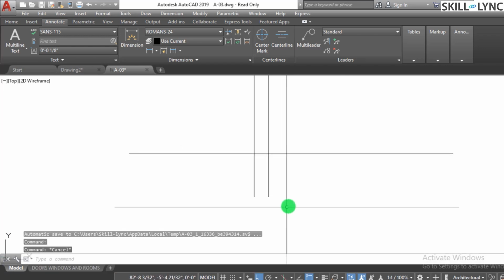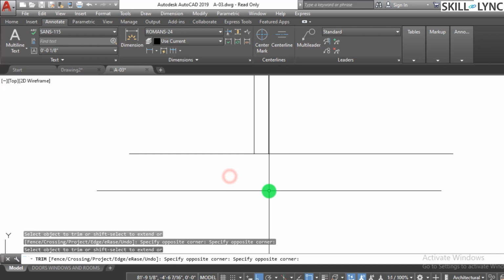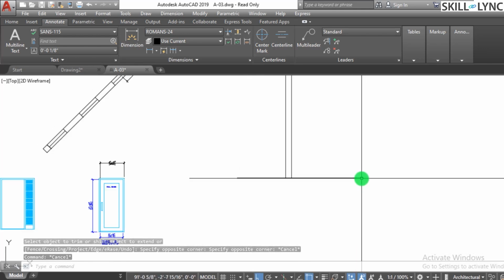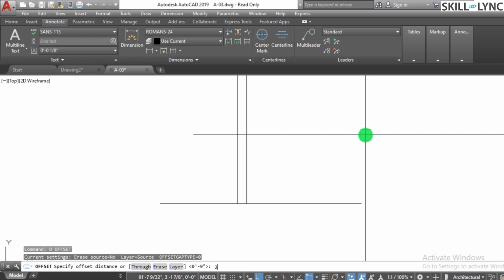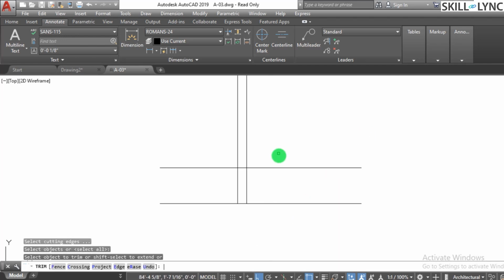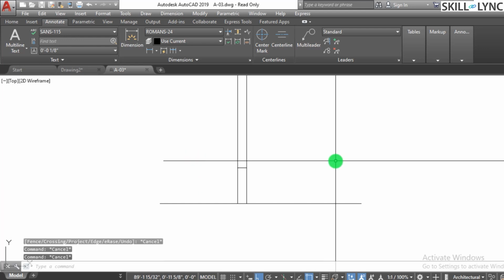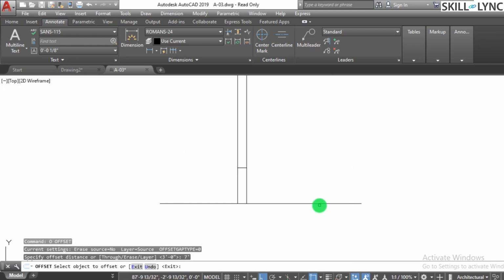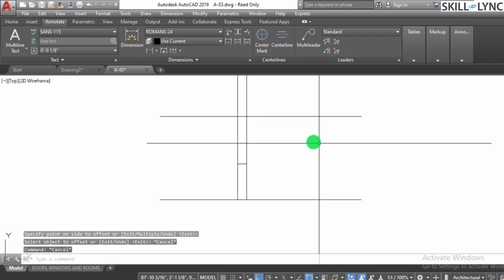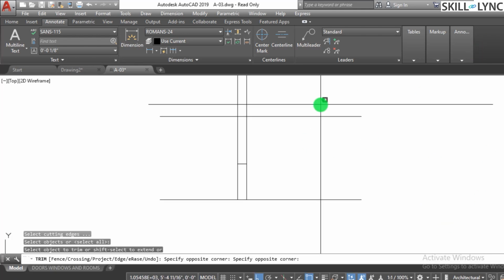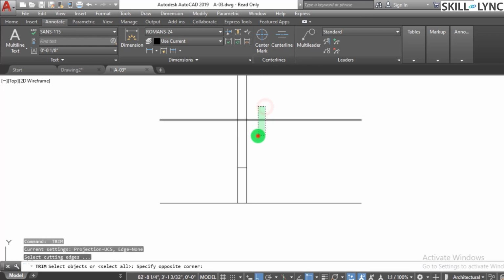So for example, I have a 9-inch wall, this is an elevation of a wall. So this is, let's say, the datum level, let's say the top of slab or whatever it is. So this line is the datum level, and from here we have the sill level at 3 feet, and then you have the lintel level at 7 feet. So I'm taking the elevation. Now friends, this is the elevation that I will be dimensioning later on.